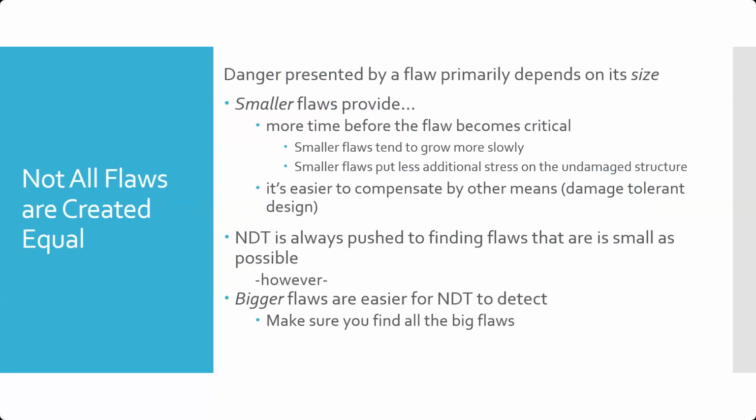So we also have to keep in mind that not all flaws are created equal. And that is the danger, different flaws have different danger levels. And danger presented by a flaw is primarily dependent on its size. That's the main qualifier in most cases. And what that means is smaller flaws are going to provide more time before that flaw reaches that critical threshold. The other part about smaller flaws, they tend to grow more slowly.